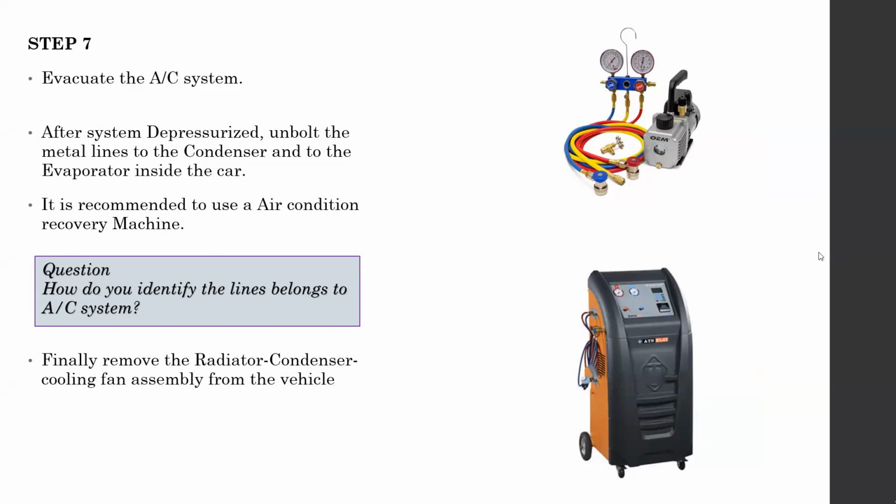But that's not the correct way of doing that. Before evacuating using a vacuum pump, the correct way is to use an air conditioning refrigerant collecting machine, or a recycling machine, which is actually expensive. I haven't seen any place using this in Sri Lanka, but sometimes some place might be using it. The correct way is to use this machine to absorb all the refrigerant.